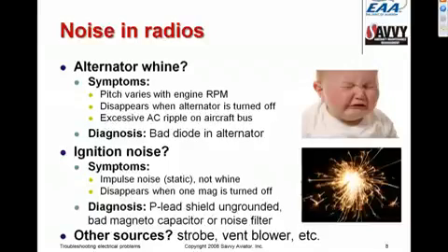But another thing that can cause noise in the radios is anything with an electric motor, particularly ventilation blowers and things like that. And again, the way you troubleshoot these things is to start turning things off, turning switches off, pulling breakers, whatever, until the noise goes away, and then you've figured out what the source is, and then you can hone in on it.